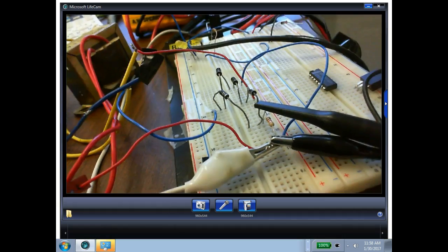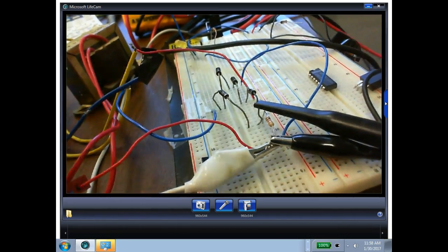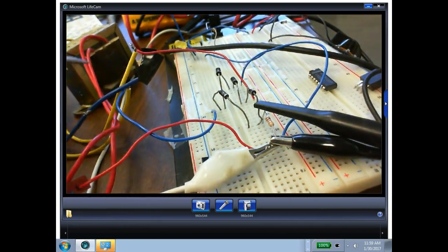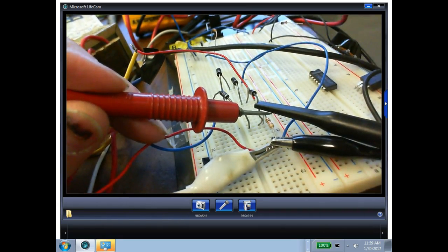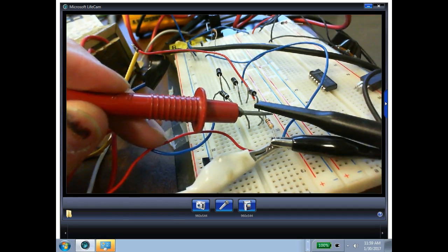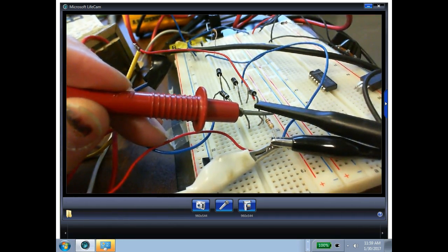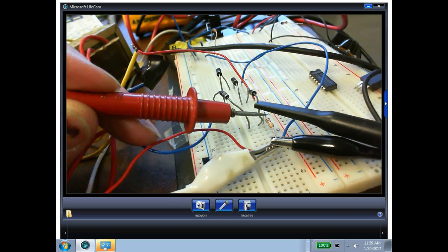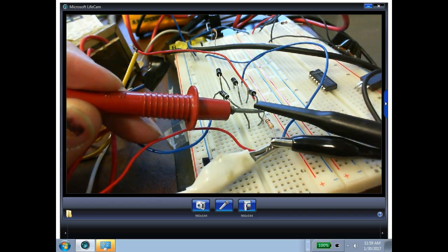It should be up here running. I got my meter hooked up. I'm going to hook across my resistor. We expected 10.5, and we're measuring 11.1. Which is pretty good because we used 110. We know it's about 120, right? You understand that? Are we okay?